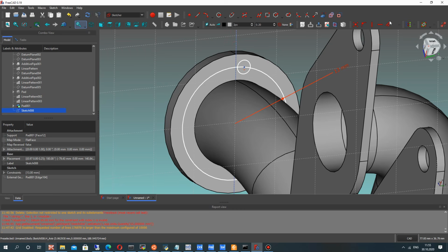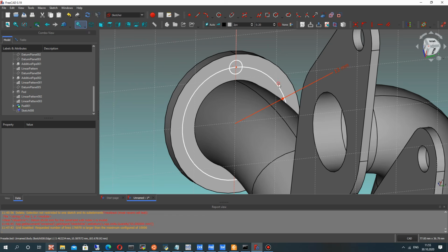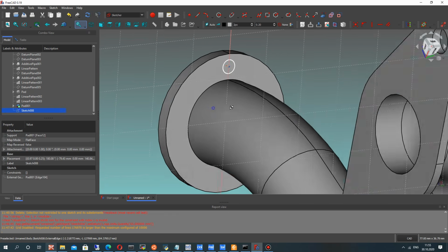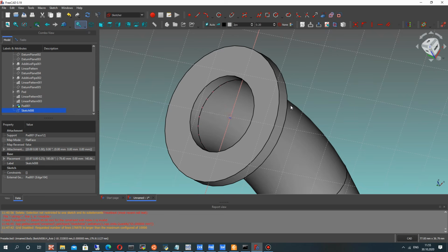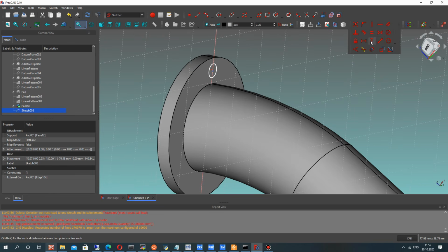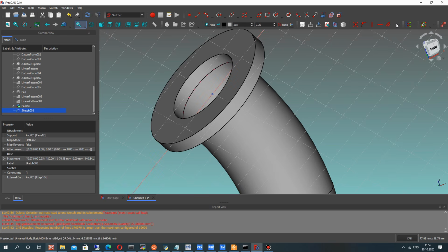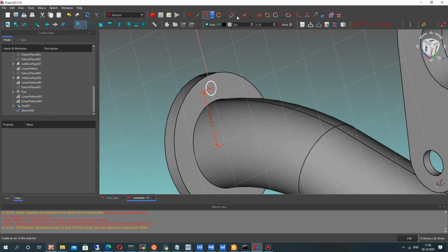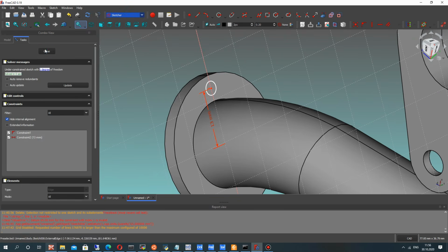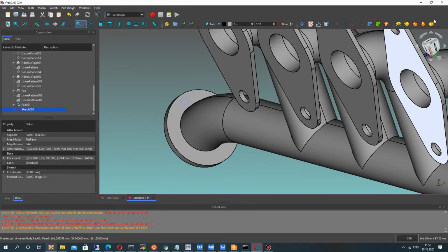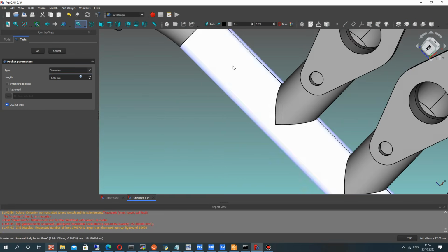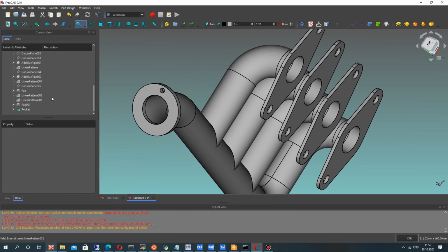And now let's just set the hole in this y direction, and let's just delete this circle and set the position, vertical position of the center of the hole here. Let's choose these 2 points. And close the sketch. After that you can make the cut operation. It's called Pocket in PartDesign, and click OK.